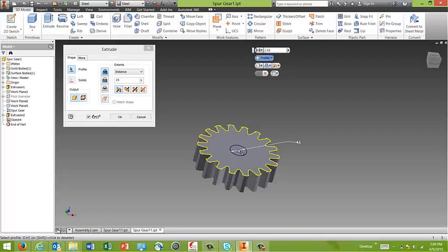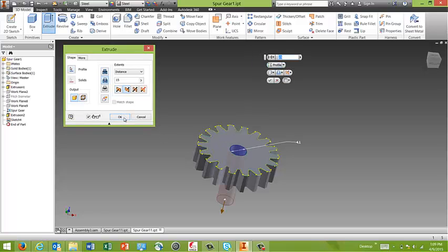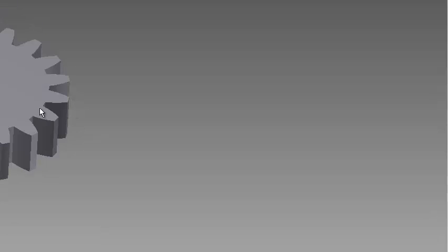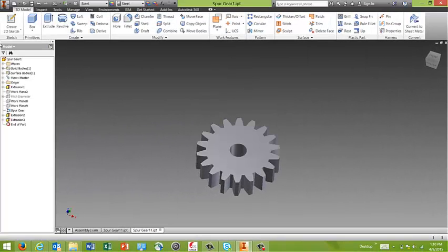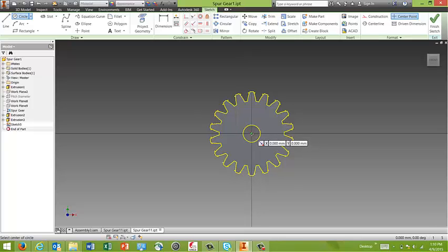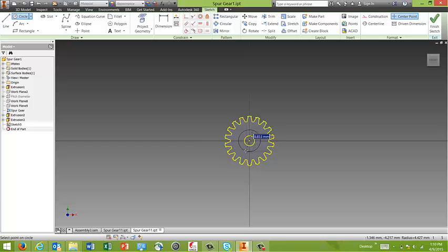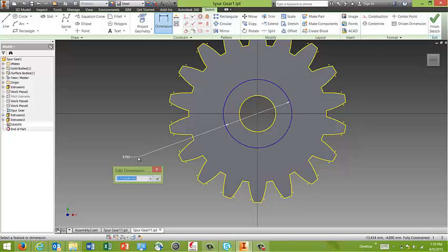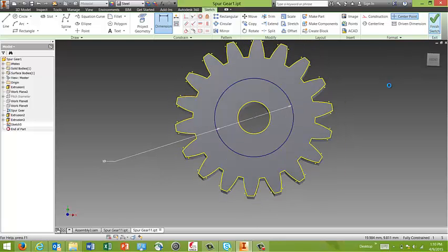And I click extrude, and I will select extrude cut over here, and I will cut a hole in the gear. Okay. With this, the gear is ready for 3D printing, and I can print out this gear and put it in. Now if you decide to have this gear press fit on a rod, to have it spin, and you want to design a boss on the gear, you can actually draw a larger circle. Okay, and determine your diameter, let's say diameter 9 or diameter 10, and I click OK.